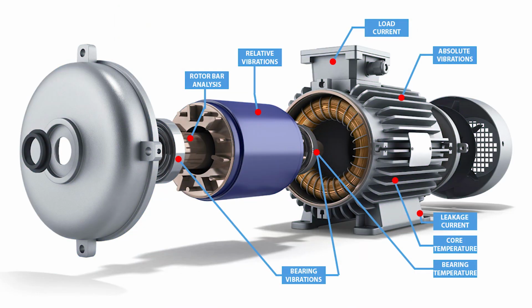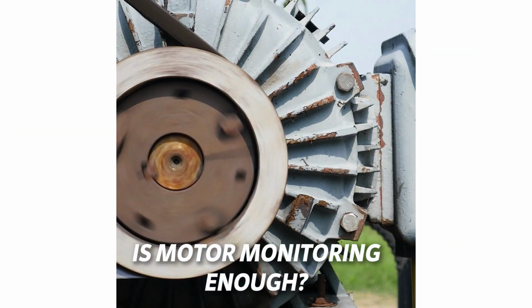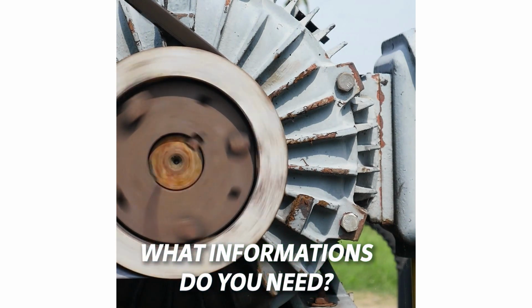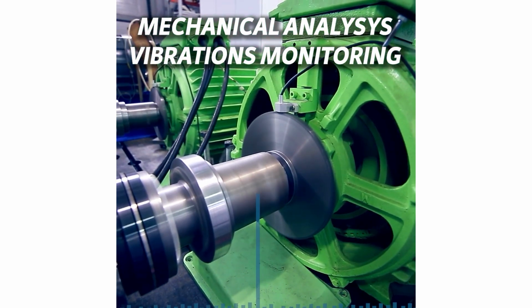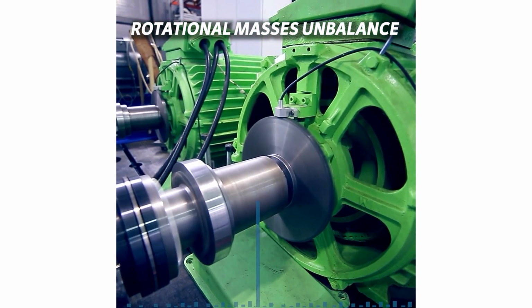Our compact monitoring solution for motors monitors absolute vibrations with FFT analysis, leakage current for insulation problems assessment, stator temperature, bearing temperature, load current level and signature analysis for turn-to-turn fault detection. For large motors, we can additionally provide relative vibrations, partial discharges, and rotor flux.